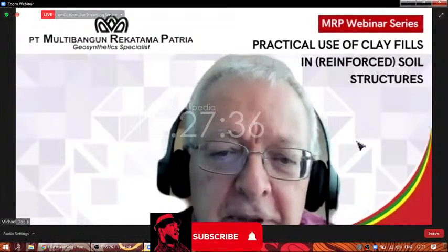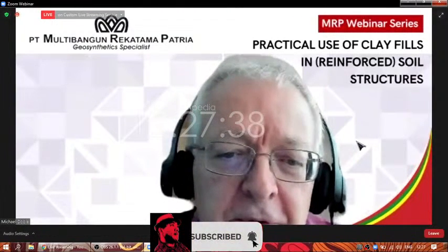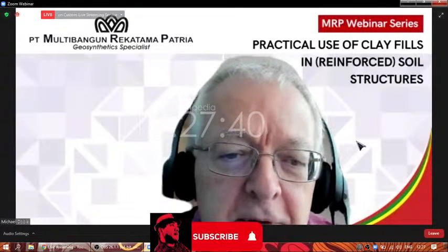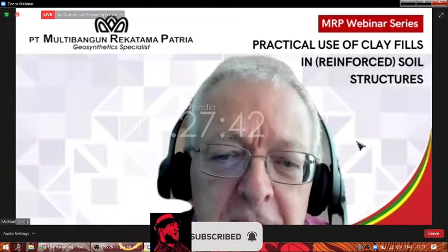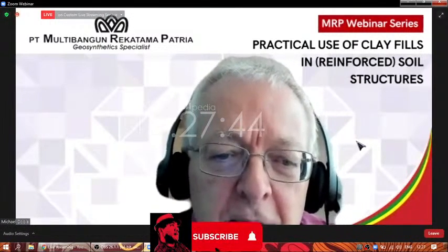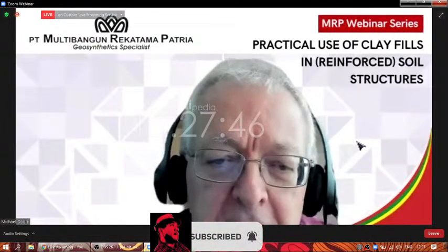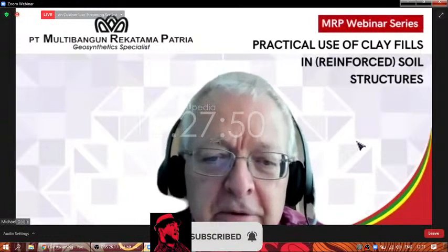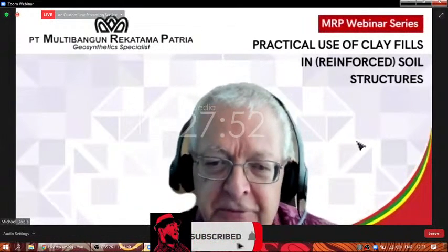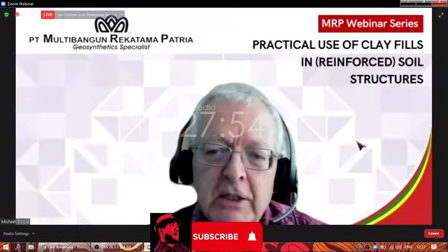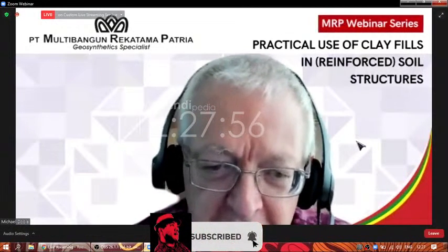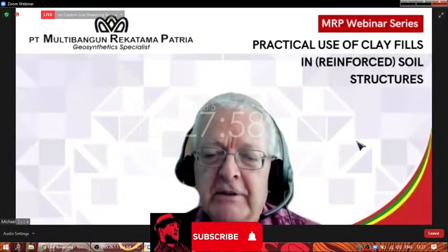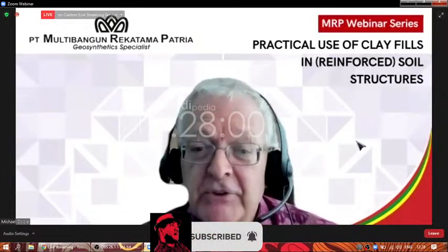How will the drainage of water ingressed through the cracks at the top of reinforced fill occur? Is it a faster rate if the permeability of the clay fill is quite low? Well, generally, as the permeability of the clay becomes lower, the rate of infiltration is going to become slower.